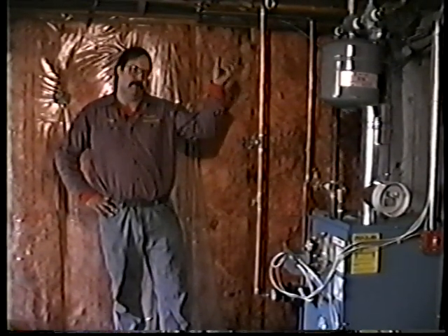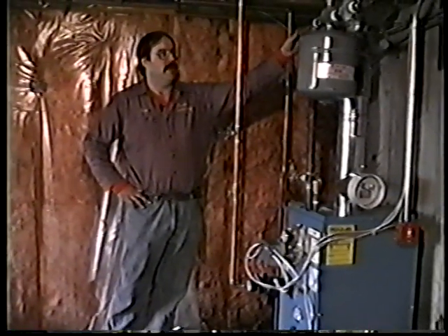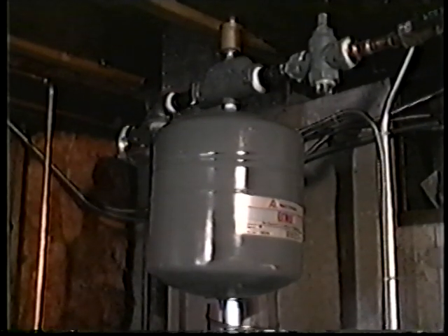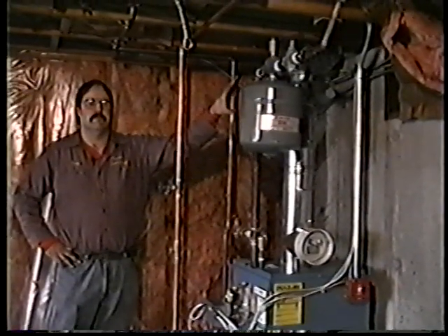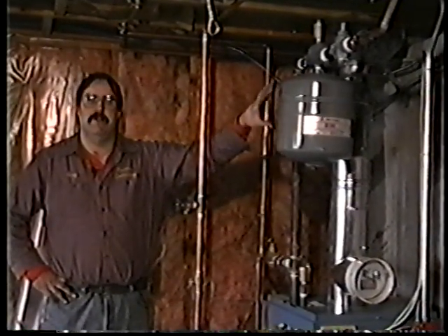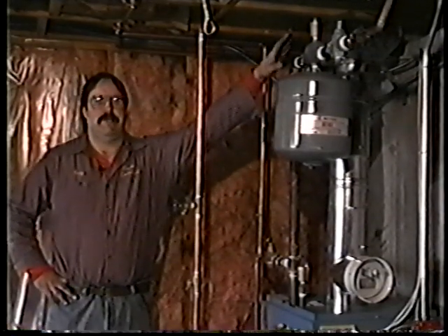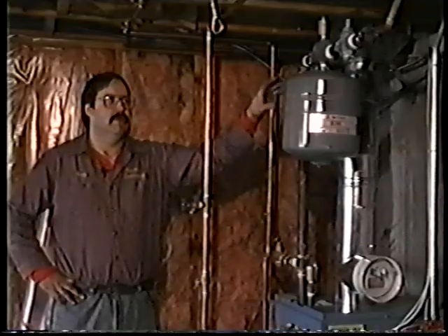The piping from upstairs we brought down into the basement area here. We ran the loop around. This is a single loop system. It comes out of the boiler on the top on the supply side. This is an expansion tank: when the water gets heated in the boiler system, the water has to expand somewhere. This tank has a cushion inside of it that allows for that expansion to take place. Air vent on the top to relieve any air that's in the system when it's running.